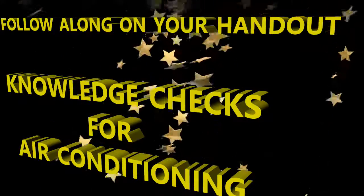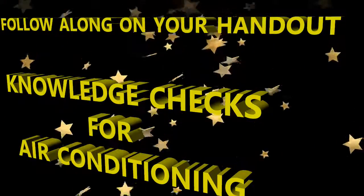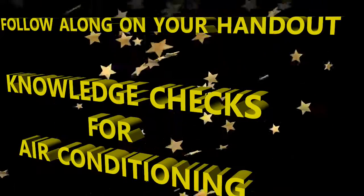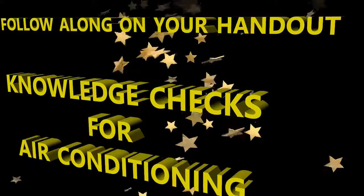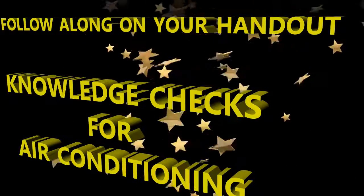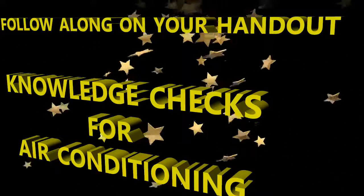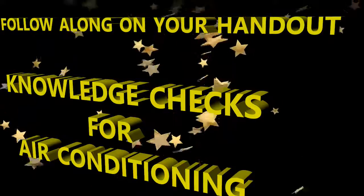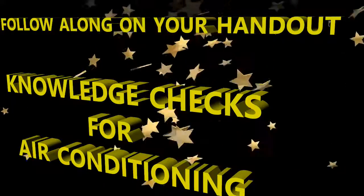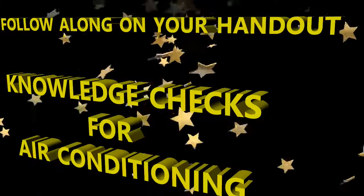What are the different ways that the avionics equipment can be cooled? Choice A, closed circuit, open circuit, and independent, or closed circuit, open circuit, partially open circuit, and cockpit supply air. Okay, so it's the latter. In a closed circuit, the avionics equipment is cooled when the skin temperature is below what temperature when the plane is on the ground? Choice A, 48.2 degrees Fahrenheit or 90.7 degrees Fahrenheit. Okay, it's actually the first answer, 48.2.